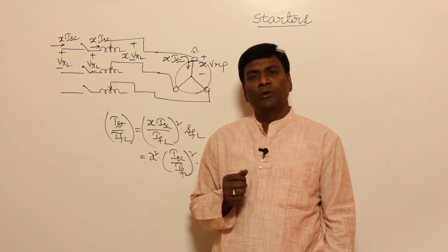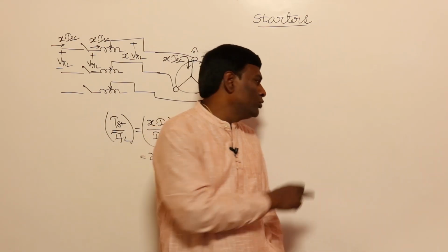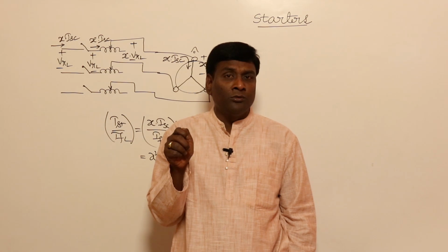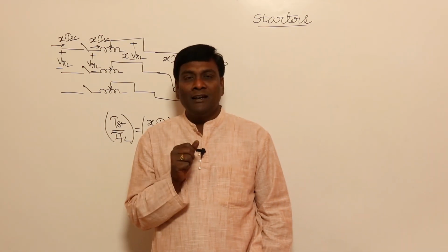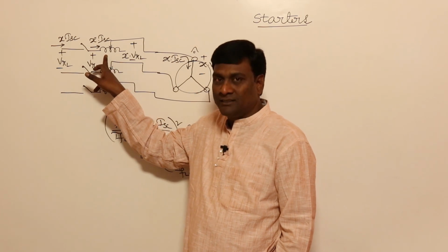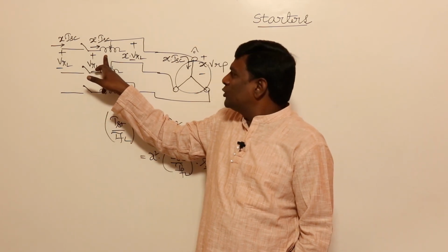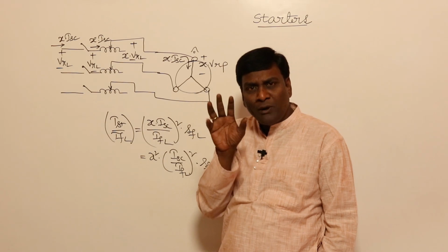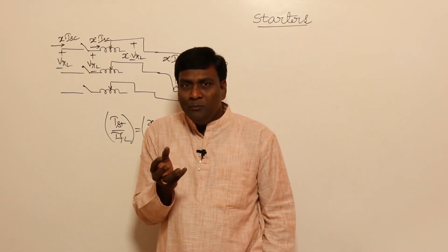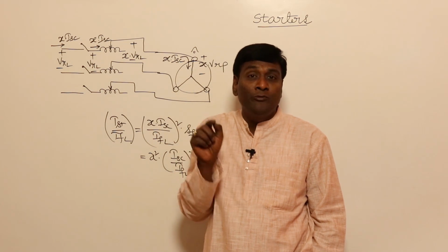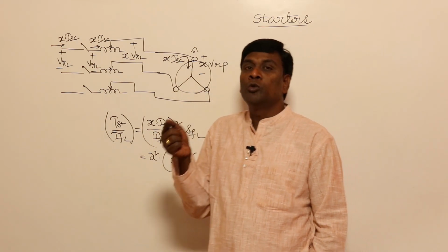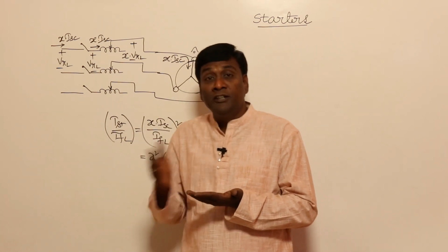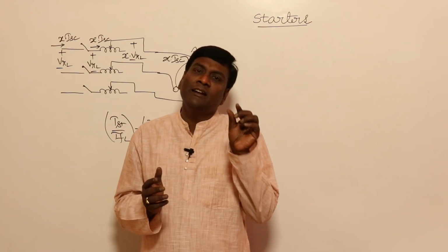For example, at your home, maybe a ceiling fan might be there. You are going to switch it on and do your work. You are not going to play start-stop. Now power loss doesn't matter here, because if it is with resistor, during starting only resistor currents will flow, so only during starting some power loss can happen. Starting power loss doesn't matter, because my machine is supposed to be working under running, stable conditions most of the time. If you switch on any motor, it can work for hours together or days together with starting only once.